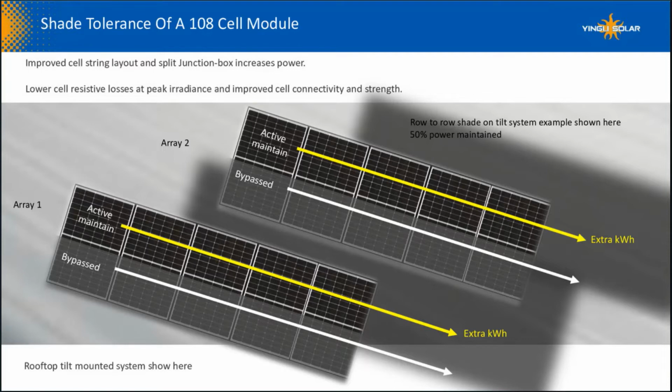In addition, our solar design is optimized to operate cooler at higher irradiance levels because resistance levels are reduced, and the system voltage drop is minimized at higher temperatures, resulting in improved system longevity. That's important because in the world of material science, there's a rule of thumb that states that for every 10-degree rise in temperature, materials would generally degrade at double the normal rate.